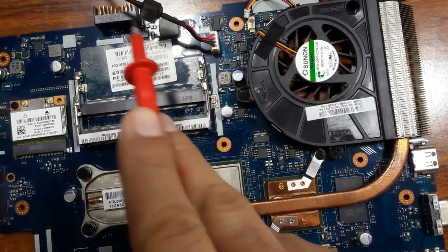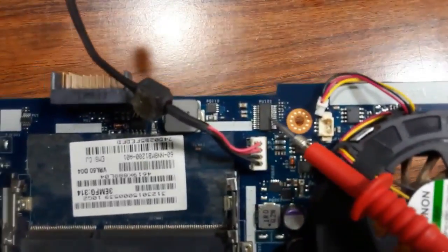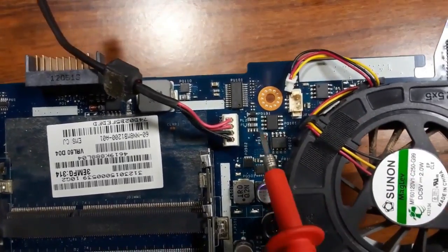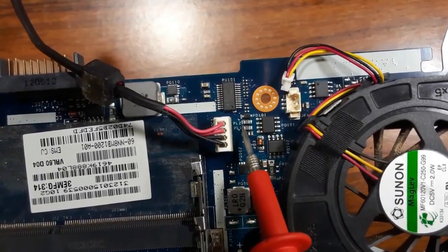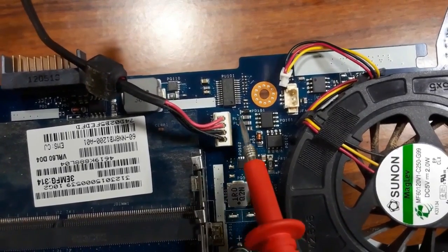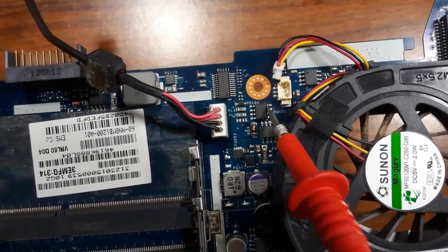Here we have the cable. Here, as you can see, this is the IC. This is the charge IC, as you can see. Here we have the coils, inductors. As you can see, we have PL. This is inductors. The 19 volt should pass through these inductors and then should pass through this MOSFET and then